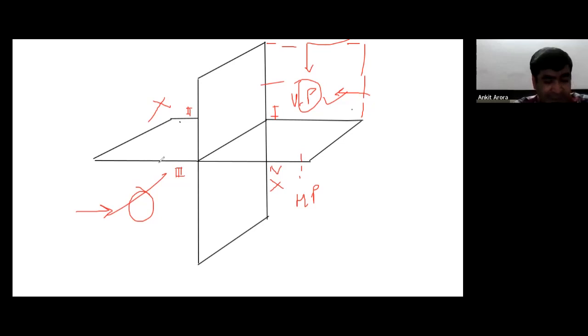So these points are usually fixed when we talk about parallel projection, and any line that is not parallel to the direction is mapped onto a line, and any line parallel to it is mapped onto a point. That is also very important for you to remember. Why? Because if there is an oblique situation where an object is inclined, then you have to manage your projection lines accordingly, like in the image that I showed earlier. Let me just go back to that particular image again so that you're able to understand these points better.